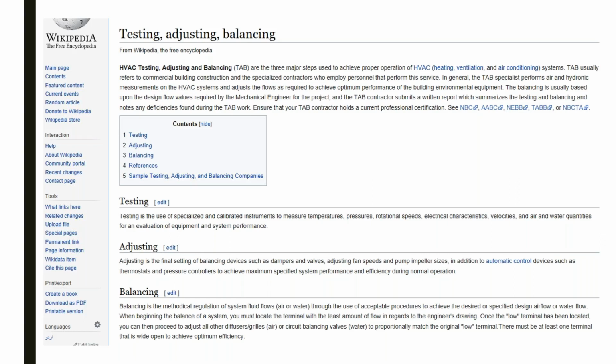I said, okay, here's problem number 1. The system has air in it. And so you're picking up the pressure difference on the pump because there's air in the suction. And so it's artificially dropping the pressure on one side that makes it look like the pump is doing the right flow, whereas it's not pumping anywhere close to the right flow. And so I had to explain to him about that. I said, okay, the problem is they haven't filled the system up very well. You need a positive pressure on the suction side of this pump in order to get the right numbers.